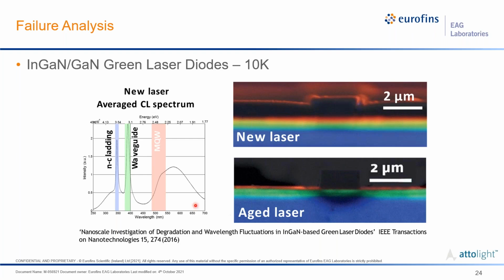They noticed that the yellow band emission also decreases within this degraded region, whereas the intensity then increases outside as well. And then the wavelength fluctuations within both the quantum wells and the waveguides are determined to be most likely due to an inhomogeneity in the indium concentrations, with possible effects on filamentation of the laser emission eventually.